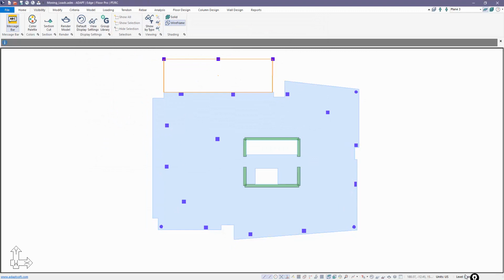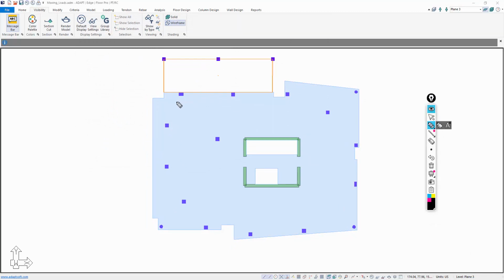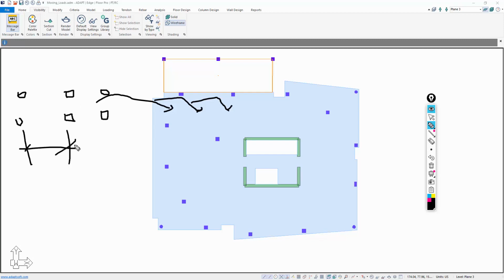Okay, and I'm going to open up a markup tool. Let's say we have four loads, and these could be represented as small area loads, basically a patch load, by some grouping like so. So this grouping I want to be able to place here, maybe move it here, and maybe I have this positioned in 20 different locations on this slab. This grouping could be an axle or an engine, let's say, with an axle in the back, similar to some AASHTO HS20 type loading where you have some distance here and then another distance here.